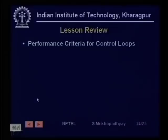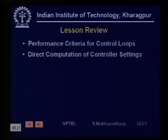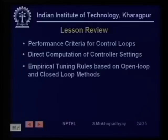So this is the end of our lesson, and what we have basically reviewed are the various performance criteria for control loops. Then we saw a method of direct computation of controller settings based on a process model, an open loop plant model and a reference model. Then we found some empirical tuning rules based on open loop and closed loop experiments that you can perform on the plant. And finally we saw a procedure called auto tuning, where we could quickly and automatically do an experiment and find out the controller settings.